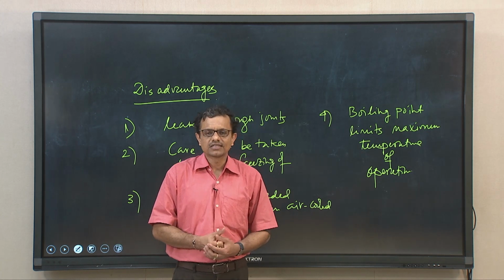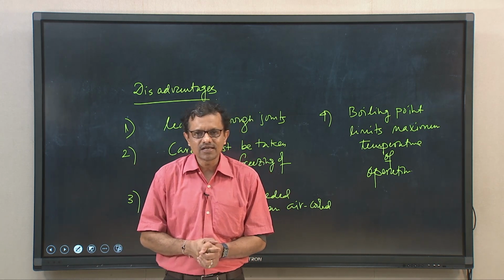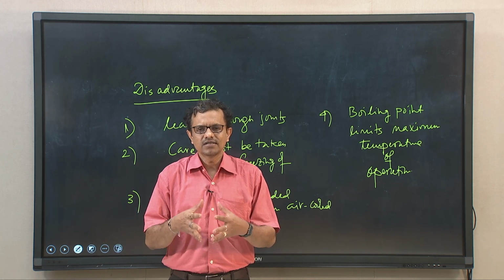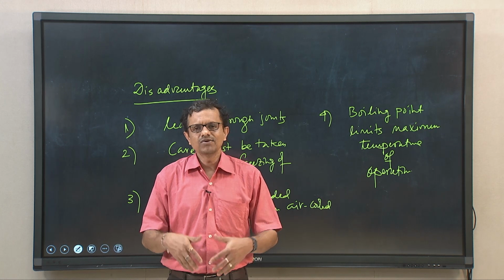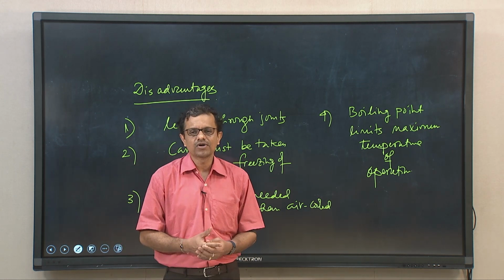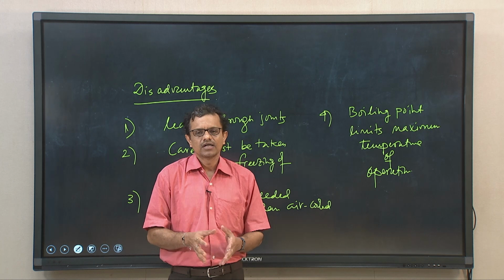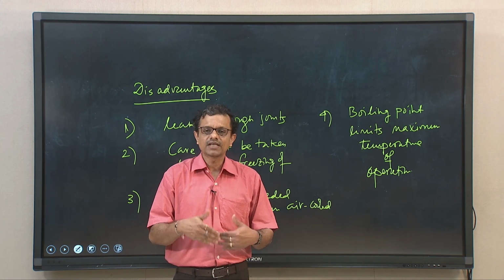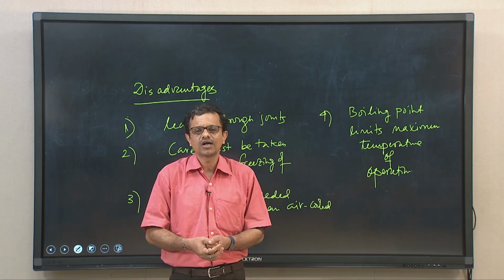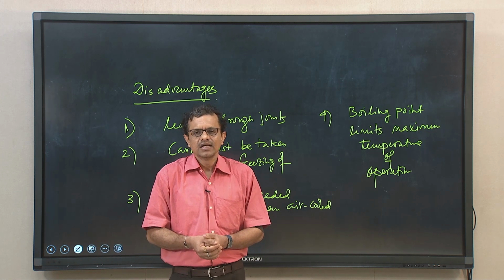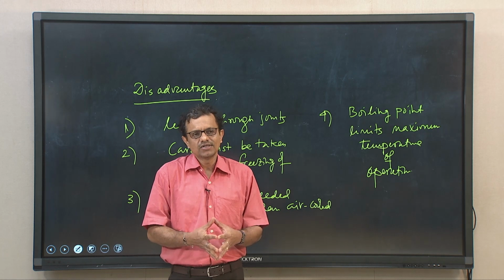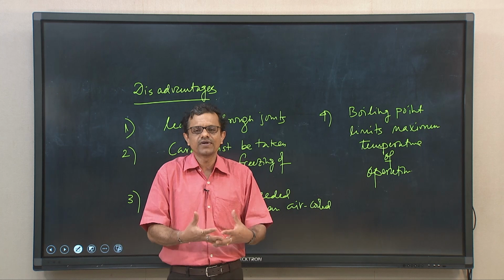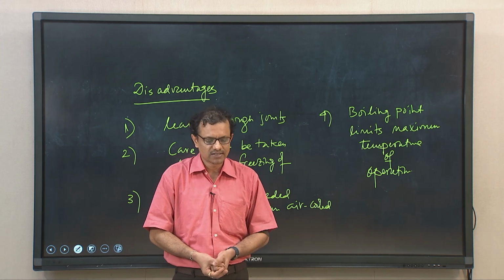So, if we summarize today's discussion, we have discussed the lubrication system, the requirement of lubricants, several types of lubrication system, and then we have talked about the cooling system, which is again an important system for an engine, because we have repeatedly discussed that we need to take away a certain amount of heat. But a designer designing a cooling system must be careful that the coolant or cooling system won't take away the maximum amount of heat, otherwise it will reduce the engine performance.